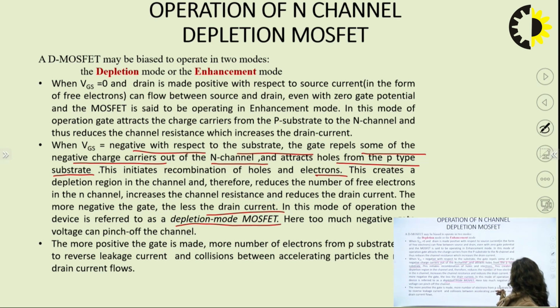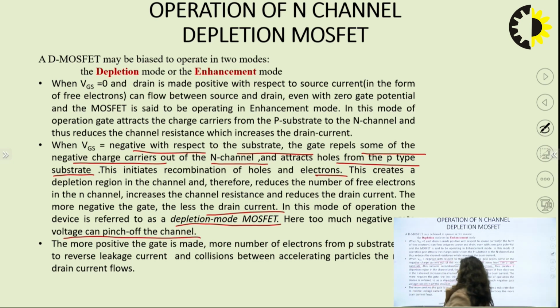Here, too much negative gate voltage can pinch off the channel. Whenever you apply VGS and make it more and more negative, that will create a pinch off of the channel.